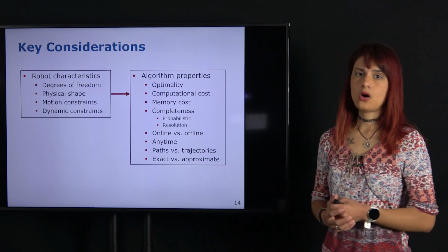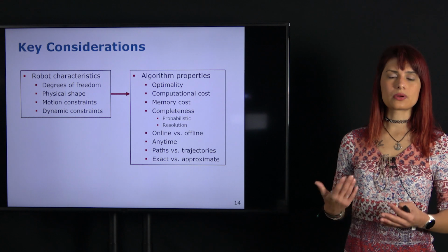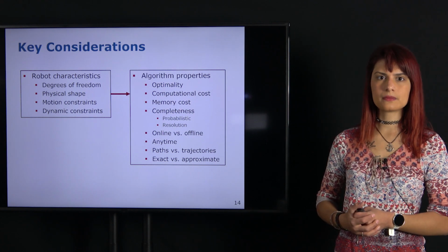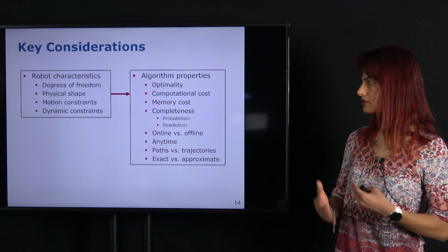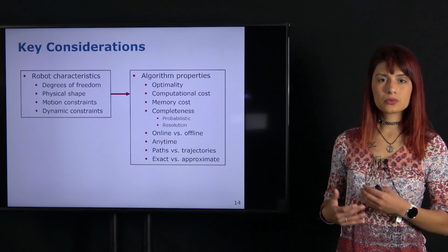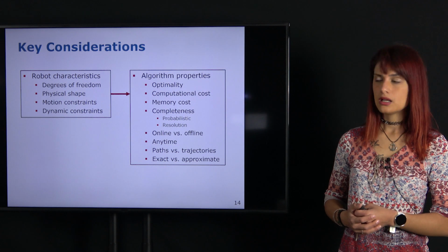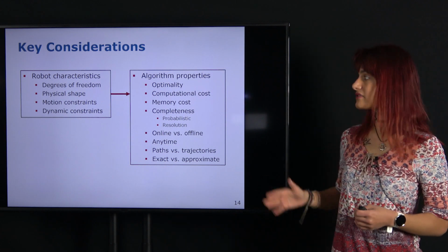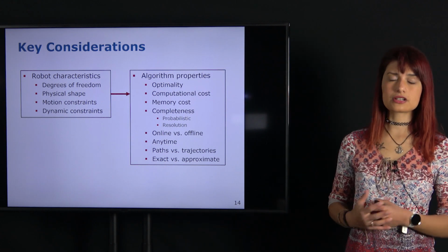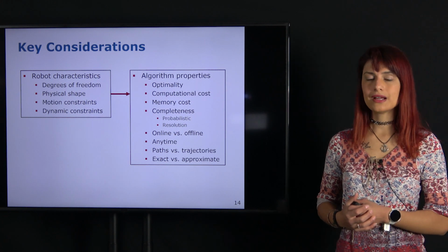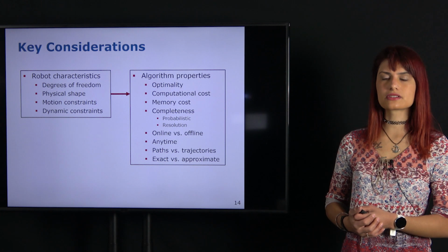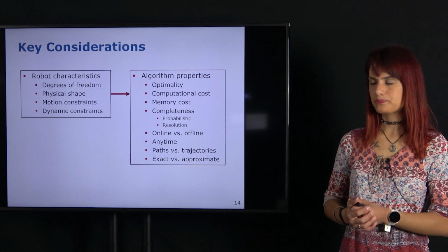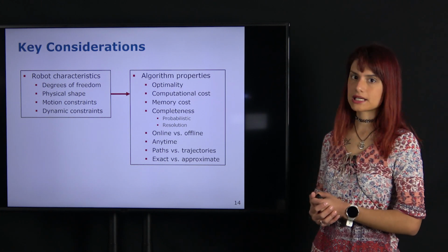In contrast, online planning is about allowing the plan to change during the mission. So if in a particular situation the robot needs to react to something, then we do want online planning. But for online planning, that goes back to computational requirements. Do we have enough resources to actually recompute the plan? And this is called replanning, recomputing the plan in an online way.